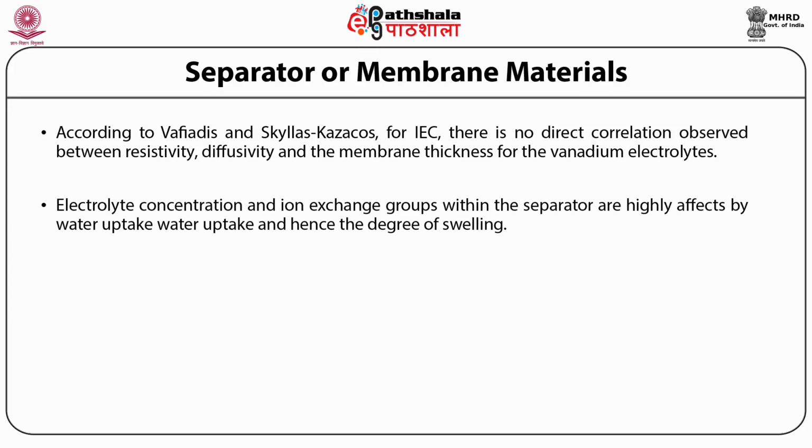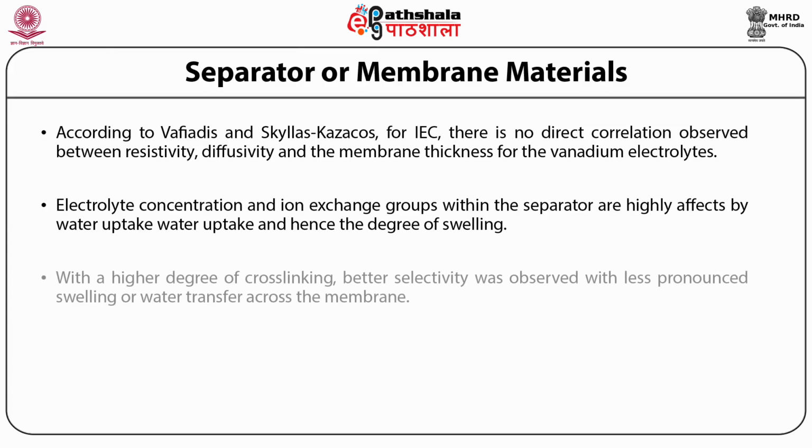Electrolyte concentration and ion exchange groups within the separator are highly affected by water uptake and hence the degree of swelling. With a high degree of cross-linking, better selectivity was observed with less pronounced swelling or water transfer across the membrane.